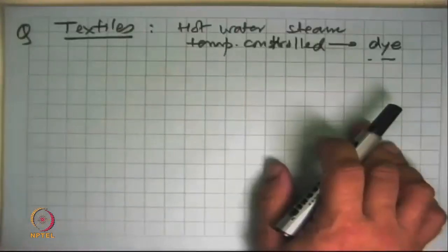So how to design that, how to get the maximum efficiency from it, how to reduce your fuel bill by optimally using that energy of steam, that's one application of thermodynamics. It will also help you decide how to collect some of the waste steam if possible and put it back, or if there is hot water with chemicals in it that is otherwise going to be wasted, can we recover some of that energy before throwing it out and use it somewhere else in the process? So thermodynamics helps us say that this much energy is possible to be recovered from this waste, and that way your total energy bill goes down and you become a little more eco-friendly.